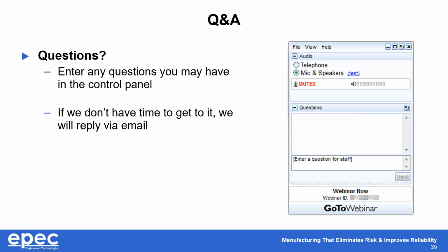Last question here that we'll touch on is what do you have for tough and abrasion resistant wire jackets? This would be an automotive application, but relatively low volumes. Typically, we'll recommend some kind of cross-linked polyethylene. It's an XLPE type jacket. That's typically rated for 125 degrees C. The majority of those are rated for up to 150 volts.